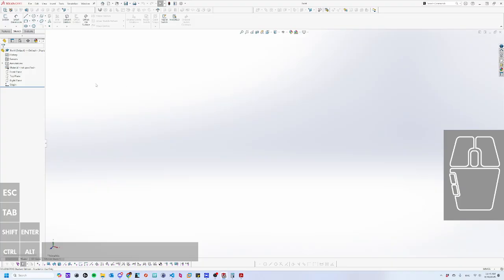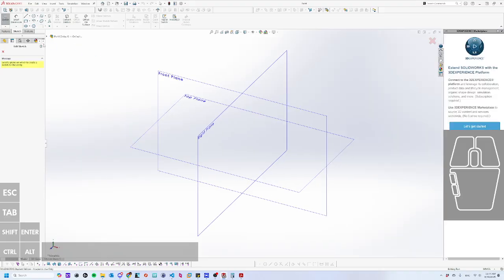Drag this off. Okay. So over here on the left is a description of all of the objects available in the drawing. So we have our 3 planes, and then we have the origin point, which is the center of the entire drawing. And to start my sketch, I'm gonna, in the Sketch tab, hit the Sketch button, which opens up here on the left.